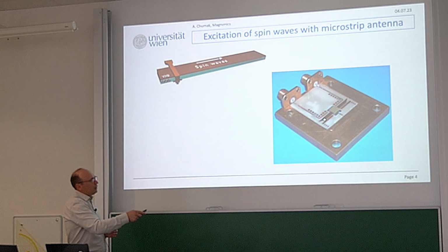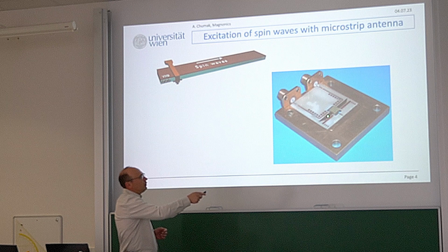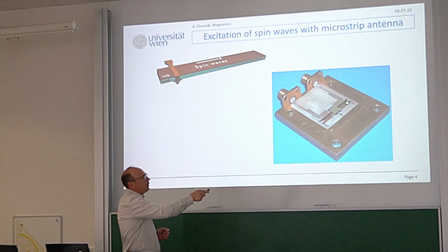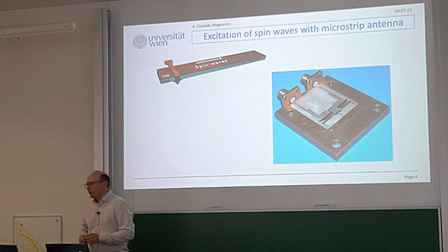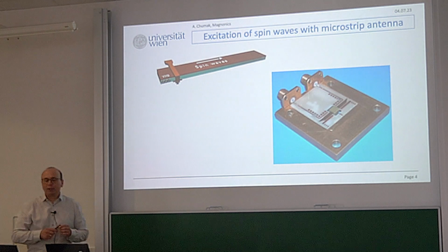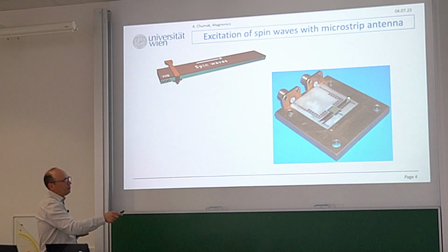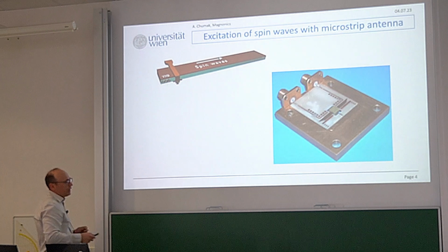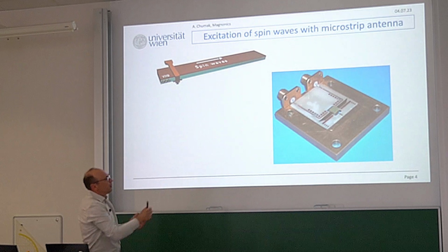So this is our yttrium iron garnet film. It's cut at some angle, 30 degrees usually. The reason is very simple: to avoid reflection. Spin waves propagate, reflect, and scatter into higher K modes, dipolar-exchange spin waves with zero frequency and zero velocities, and more or less all energy is absorbed at these edges. It doesn't reflect. There are other ways to make absorbers.